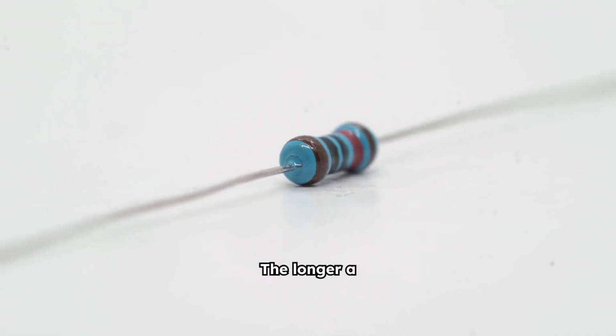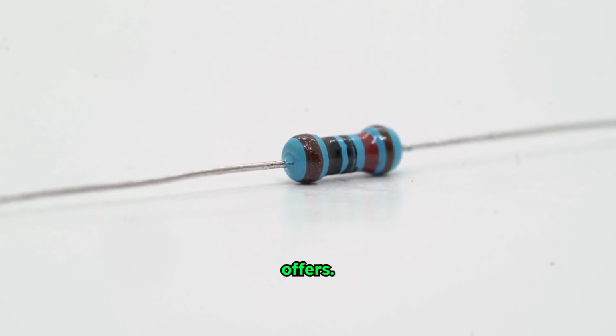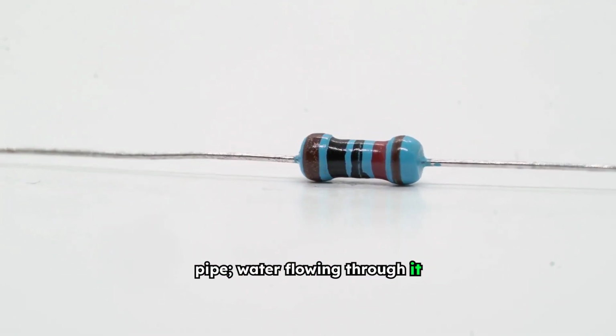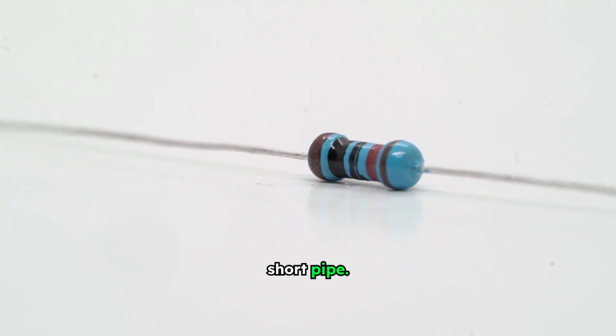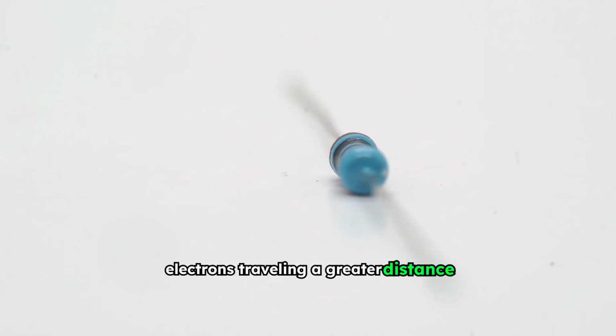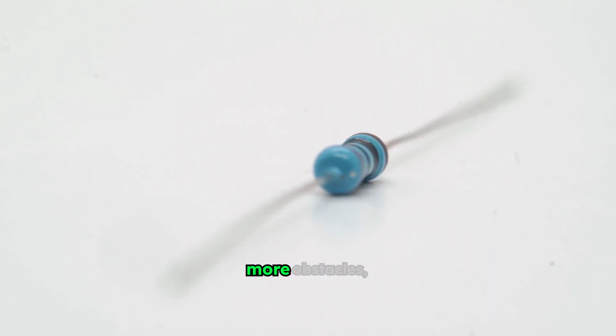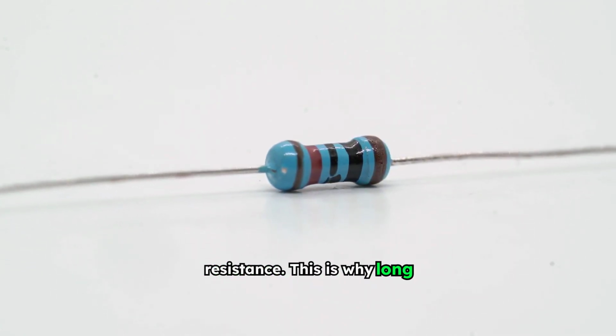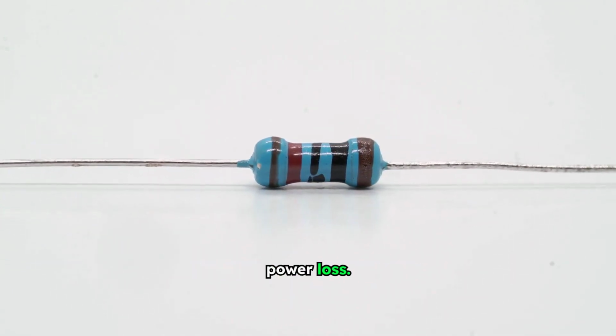The longer a conductor, the more resistance it offers. Imagine a long, narrow pipe. Water flowing through it experiences more friction than in a short pipe. Similarly, electrons traveling a greater distance through a material encounter more obstacles, leading to higher resistance. This is why long transmission lines experience some power loss.